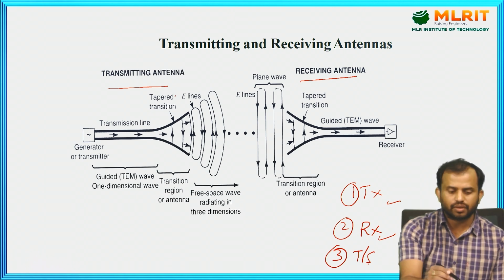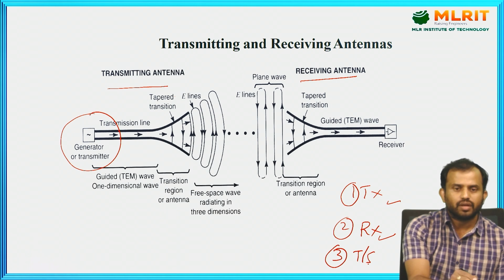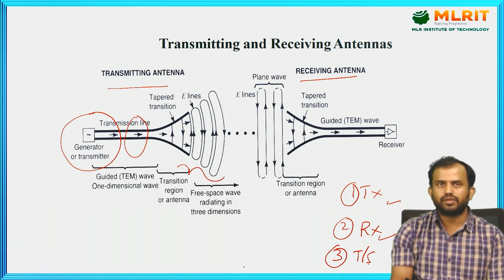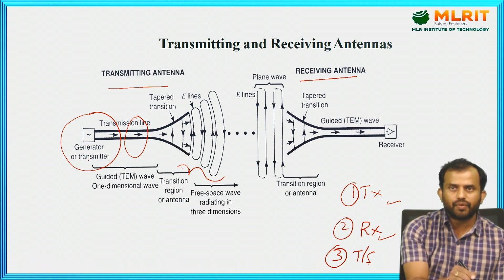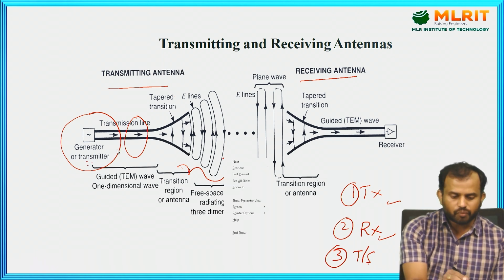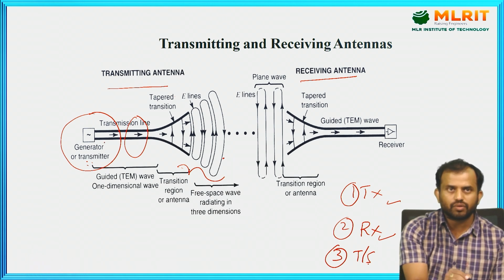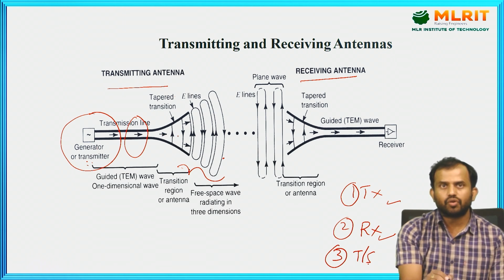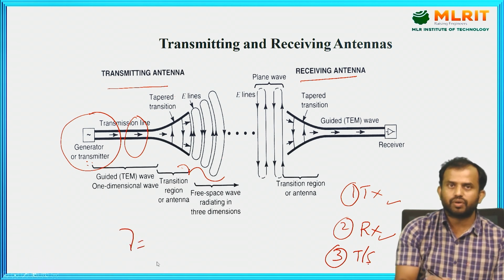What is the transmit section? When you look at the transmit section, we have a generator block, a respective transmission line, and at the same time the signal propagation into the medium. Whatever frequency and supply we give to the antenna can be converted into electromagnetic wave values only with the help of the transmission line. That is, the amount of electrons flowing, the conversion of electrical current into electromagnetic waves. Here we use the propagation constant value because the signal is propagating.